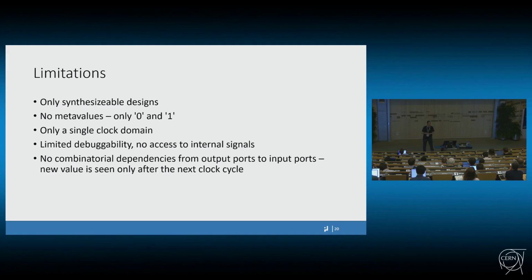For now, there's only a single clock domain supported, and as you cannot just open the hierarchy in the simulator, because there is no more hierarchy, you cannot just access internal signals in the design. So there's limited debuggability. And because we transformed the design under test into a cycle-based evaluation, there may not be any combinational dependencies from the output ports to the input ports.